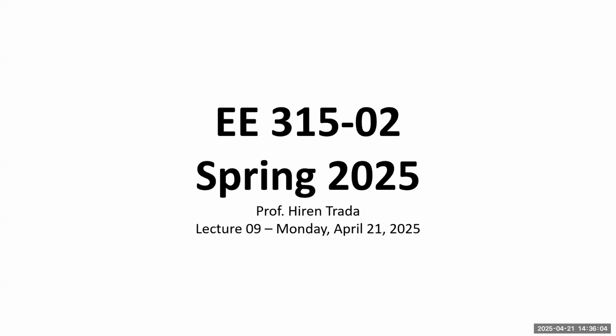Okay, good afternoon, everyone. So today I want to do an example of the load line analysis technique. As a brief recap, let's bring up the load line analysis. This is a very important technique because we will use this again for Zener diodes, we'll use it for BJTs, we can use it for FETs, MOSFETs. It's a graphical analysis technique that allows us to determine the Q point.